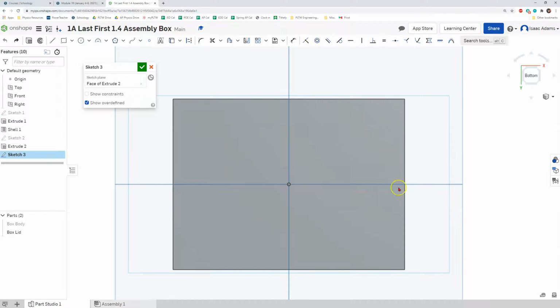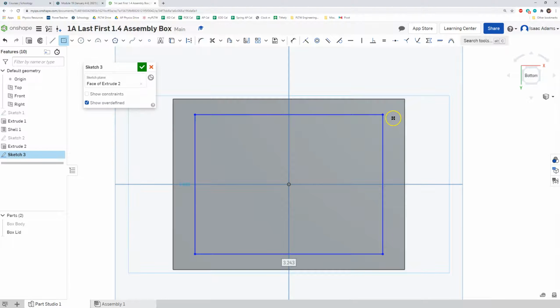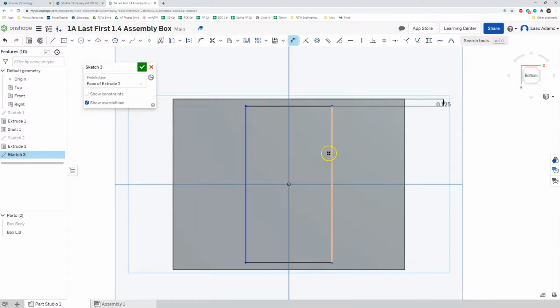So I'm just backing up and removing that shape, and instead of using the corner rectangle, I'm going to use the center point rectangle and just click it into place. And the benefit is that each of these is the same distance from the center, so when I use the dimension tool to put this 1/8 of an inch off, it does it to the bottom as well.